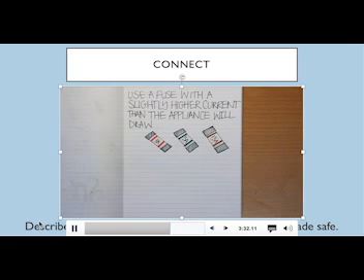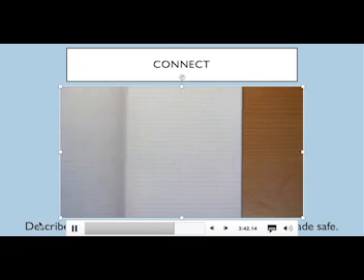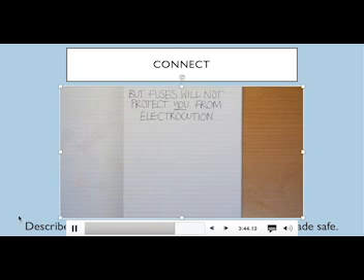This means that the fuse will blow if a fault draws even just a small amount of extra current. But using too large a fuse could mean that it will never blow, despite a dangerous fault developing. However, the current at which a fuse blows is still likely to be about 1,000 times higher than the current needed to kill someone. So although they make devices safer, fuses are generally unhelpful in preventing a person from being